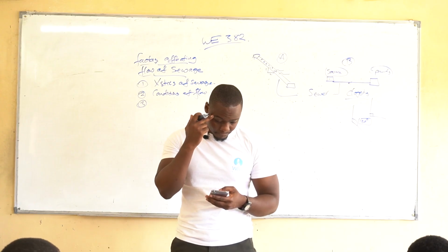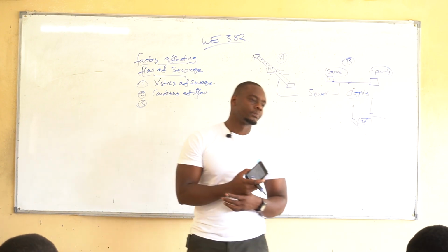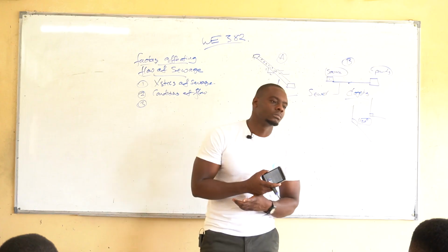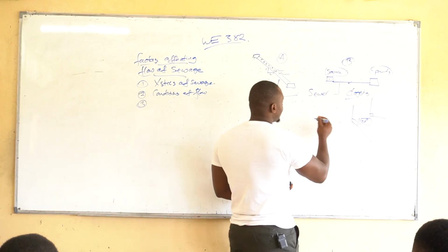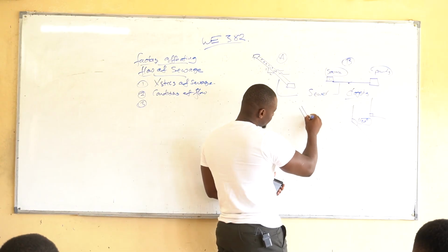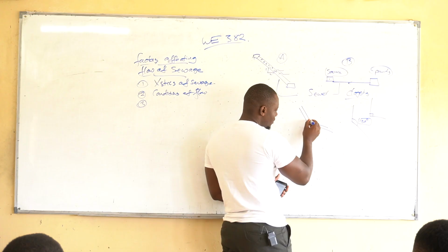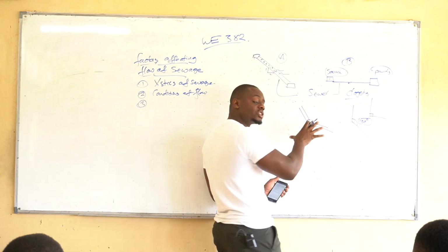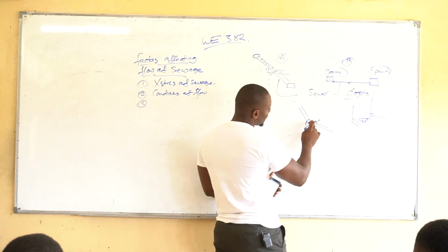Instead of using bending, that's the reason why they put a manhole close to where the direction changes, so you can bend there. Ideally, yes. If a pipe is coming in and just has a bend like that, it restricts how much can go through, and there's so much that could go wrong.